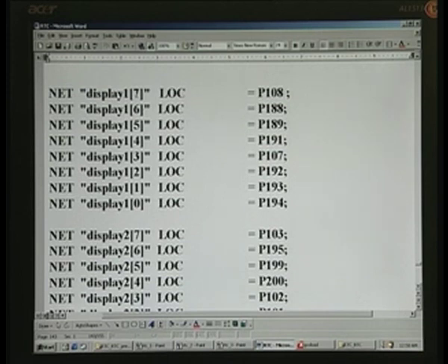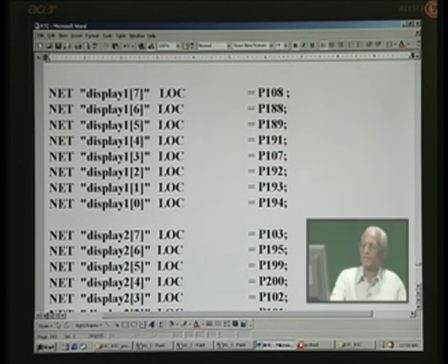And here you note that you need to do bitwise, because there are 8 bits. The system cannot do it all by itself. You have to assign every bit a unique number, and note that these numbers are all not in order, so it all depends upon how you have connected your extension port from the FPGA board, on the FPGA board.